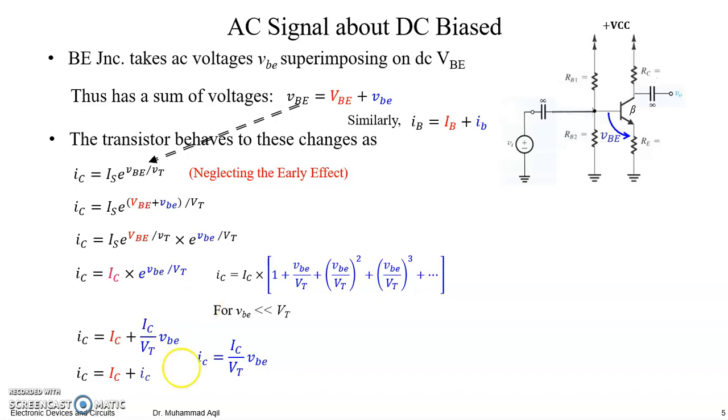So it means we can change this multiplication factor of the input AC signal by biasing the transistor to a desired location, right? Previously we considered only the maximum undistorted amplification in amplifier design. So we can consider the designed amplification of the AC signal in our DC biasing selection process.